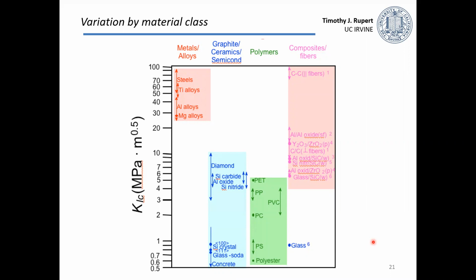Ceramics might even be better when in compression. Tension's a different thing. And that comes about mainly because of this fracture toughness. So metals are the clear winner in terms of fracture toughness. They have very, very high toughness values, an order of magnitude higher than ceramics. Okay. And this is representative of the fact that metals are generally ductile and ceramics are generally very brittle.